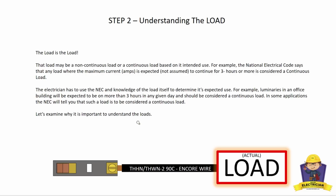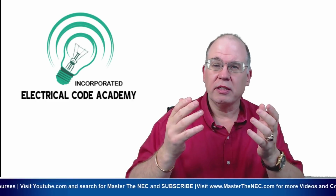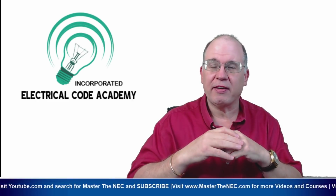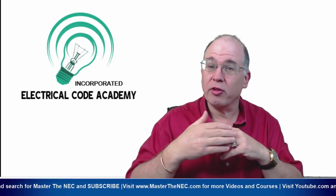Now, let's talk a little bit about the load, because that was step 1, talking about the actual terminal listings and everything like that. Let's talk about the load. The first thing to remember is load is the load. All right, and I can kind of paraphrase this slide. The load is the load. If I have something in the code that tells me to take something as a continuous load, it doesn't change the load. The load is still the load.